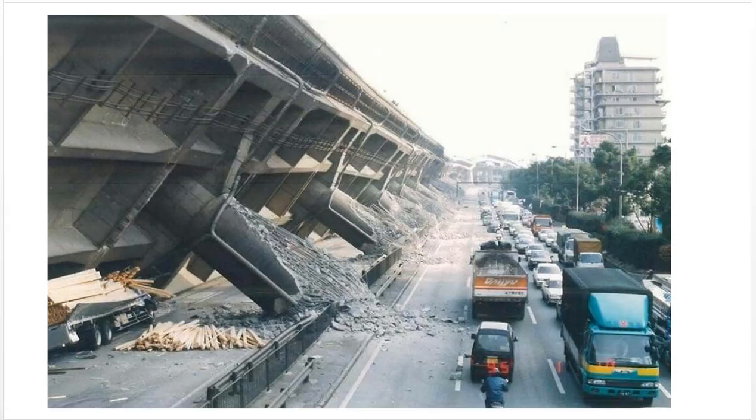This is almost unreal. You see the overturning moment basically destroying these giant columns. So the idea of showing you these pictures is just to show you that it is very important to design columns not only for their axial loads but also for lateral effects that create bending combined with axial. So in the case of this column here, what you have is a bending moment, shear, and axial.